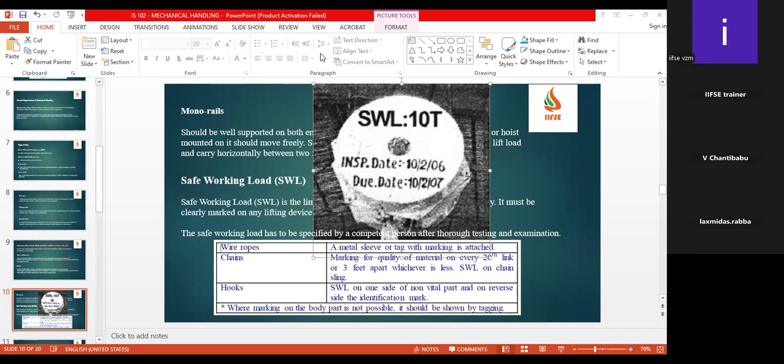Again, there is a point of discussion, because these kinds of activities are critical activities. If you're putting in an EOT crane, it means you are definitely lifting more than 1 ton. And 1 ton is sufficient to kill a person if it falls from height. So for these kinds of trainings, we have to take out all the critical activities. We should plan refresher trainings once in 6 months.